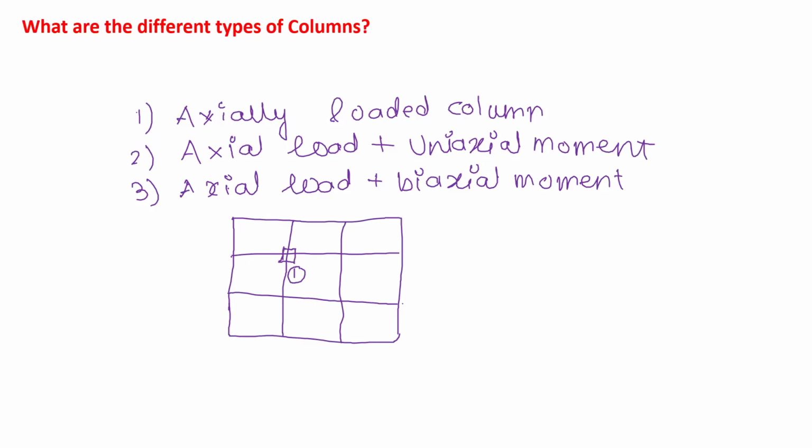Interior columns are generally axially loaded. The columns which are on boundaries but not at corners, at the periphery, are axial load plus uniaxial moment.